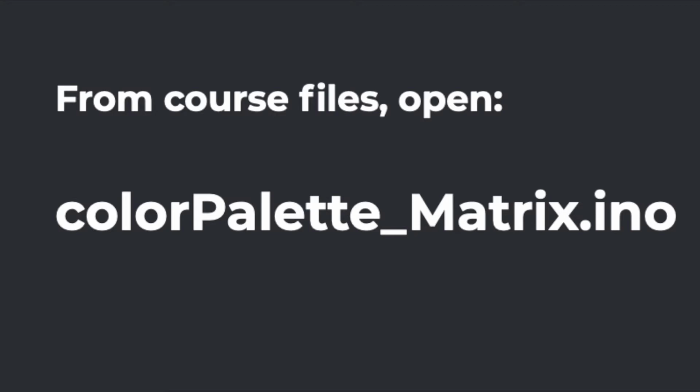If you've got your example sketch loaded, double-check all your connections, making sure that power and ground are not in contact with each other. If all's well, plug in the power supply and then your Circuit Playground, and you should see the matrix light up with our test pattern. If you don't see that, stop immediately, unplug the Circuit Playground and then the power supply, and recheck your connections. If things still aren't working, come to our office hours. We'll be glad to help.